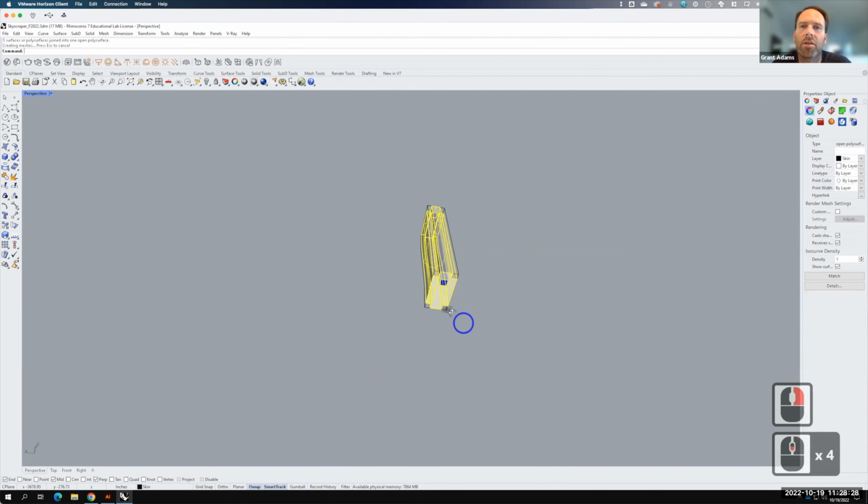That's excellent. Let's go ahead, since we're here, we don't really need the full elevator shaft. And again, this is why I did a save as, because I'm kind of chopping this up. I'm going to go ahead and take it, and I'm going to type trim and get rid of the elevator shaft in the middle. So let's get rid of these surfaces like that. I'll hit enter to finish. And now I could actually join the top of the elevator core with this building, and that all becomes one.